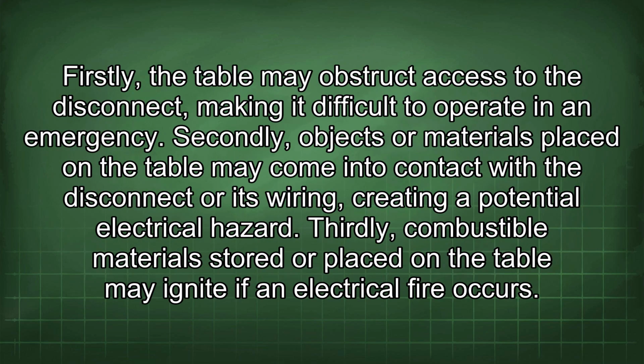Firstly, the table may obstruct access to the disconnect, making it difficult to operate in an emergency. Secondly, objects or materials placed on the table may come into contact with the disconnect or its wiring, creating a potential electrical hazard. Thirdly, combustible materials stored or placed on the table may ignite if an electrical fire occurs.